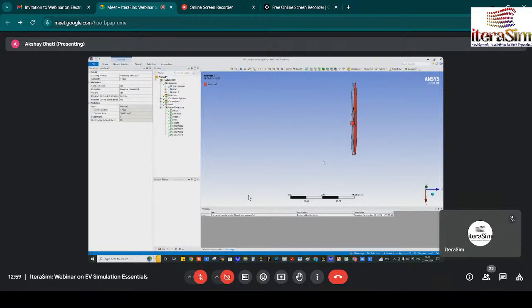Interface means you connect the bodies using, here in mesh, the name interface, so that in Fluent setup you can connect these different bodies, so that it can provide continuous flow. If you do not connect these bodies using the interface, there would be no continuity of the flow, so Fluent would not start. If you don't want a contact region, you have to give an interface, so that you can connect it.